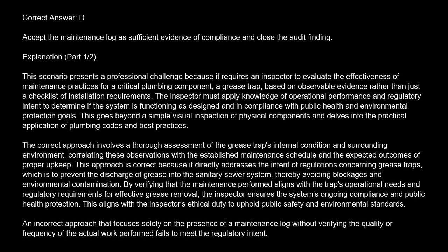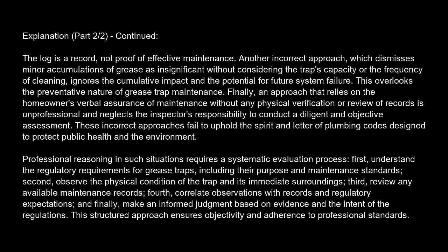An incorrect approach that focuses solely on the presence of a maintenance log without verifying the quality or frequency of the actual work performed fails to meet the regulatory intent. A log is a record, not proof of effective maintenance. Another incorrect approach, which dismisses minor accumulations of grease as insignificant without considering the trap's capacity or the frequency of cleaning, ignores the cumulative impact and the potential for future system failure. This overlooks the preventative nature of grease trap maintenance.